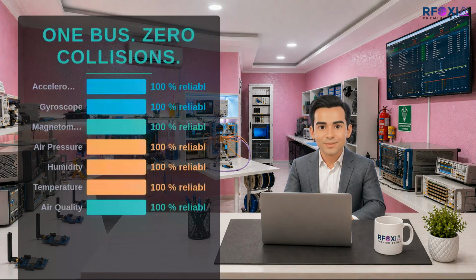That is the distinction I want you to carry out of this video. Bus conflicts are a design problem. Dedicated address assignment is the design solution. The right time to solve it is before the schematic is drawn, not after the prototype stops responding.